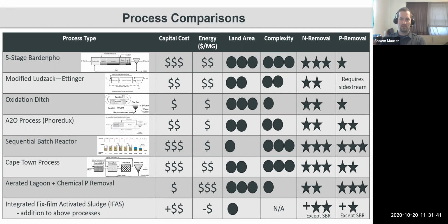One that we've seen growing a lot for phosphorus removal particularly is sequencing batch reactors, because you can tune that sequence in order to hit specific targets for nutrient removal. It's mainly just adjusting the timing of that process, with some additional sensors for ammonia and phosphorus in the stream to detect whether you're hitting your targets or not. Really, it's just changing the different processes' timing in order to get better removal.